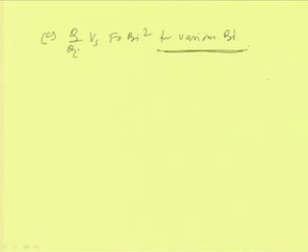Okay. So, we already have that Biot number is 0.047. Already we have seen that 1 by Biot number is equal to 21.5. So, Biot is equal to 0.047, and as I was telling, Biot number is very low, much lower than 0.1, and therefore the lumped parameter model is applicable in this kind of case.